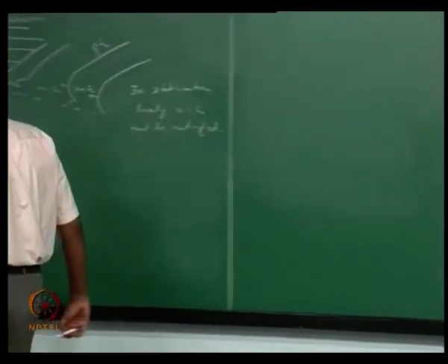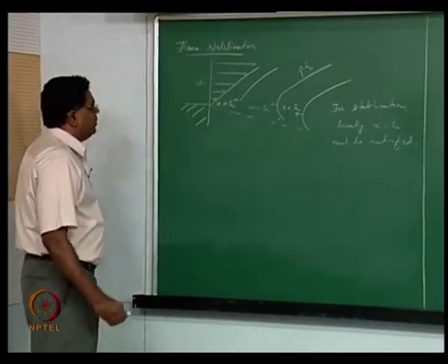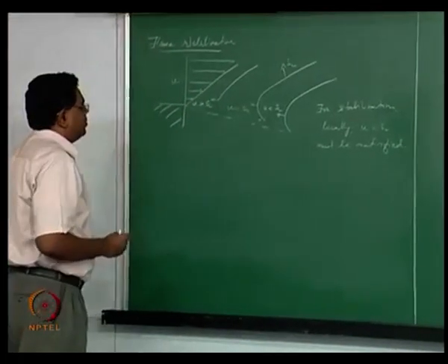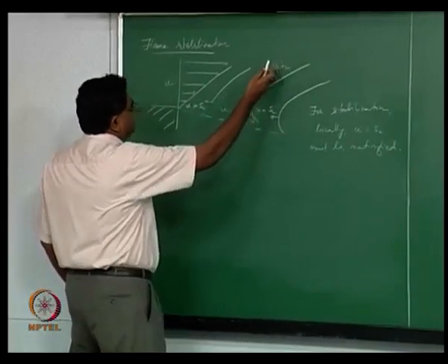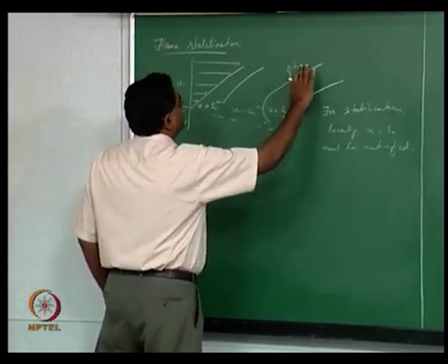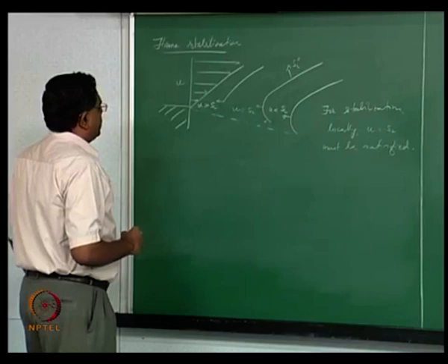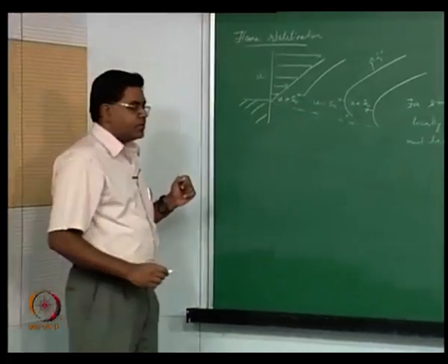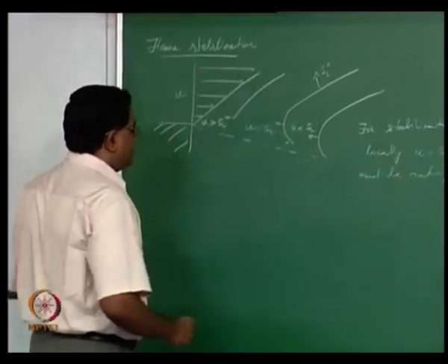So we've been looking at how this flame stabilization happens, and essentially what that means is you have a linearly increasing velocity profile, but you also now have a flame speed that continues to decrease from the value of SL naught. It decreases because of the heat loss to the burner as one of the effects, and the other effect is the dilution from the ambient.